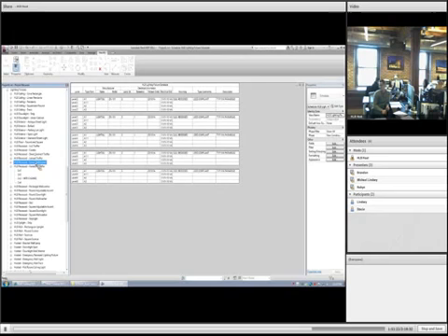So this brought me to a question that I had yesterday. When I originally documented, we had no symbols, so I went to manufacturers and just got something that was close. In terms of our project organization, I had a separate folder that said fixture families, and I loaded each of those individually into our project. I renamed it F2, so that I didn't have all of these in a project, I had only what I had used. Not a bad way to go.